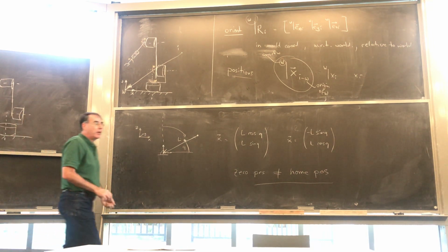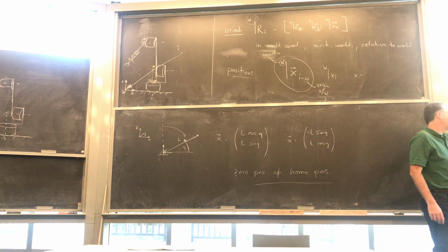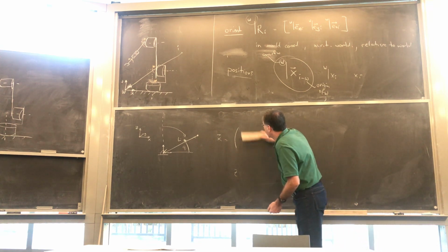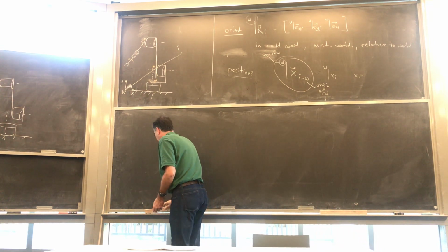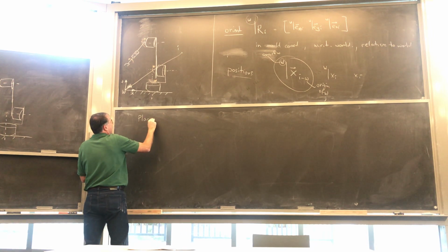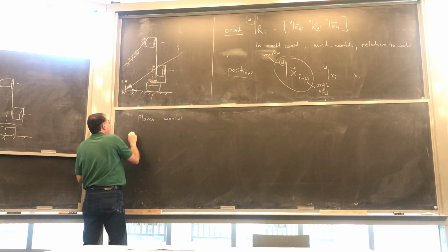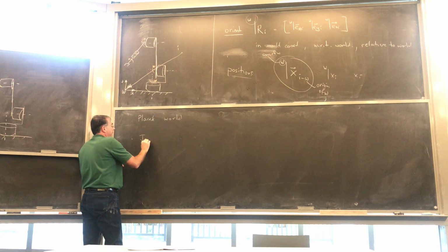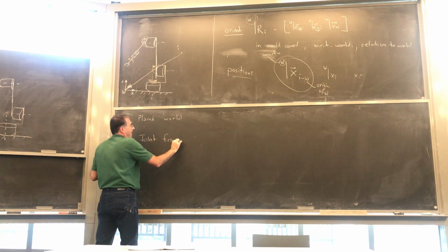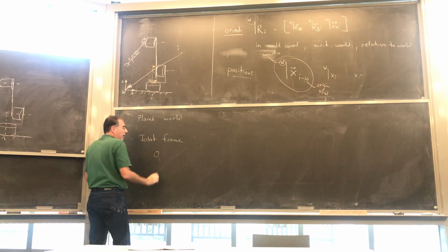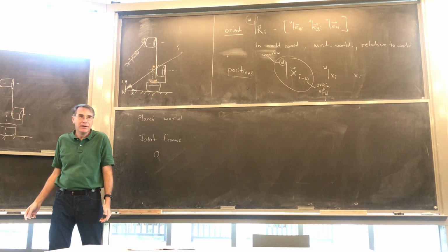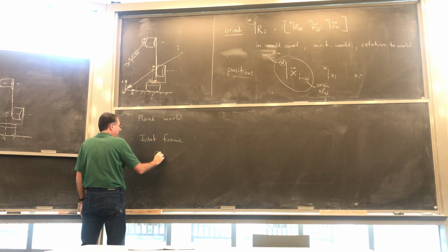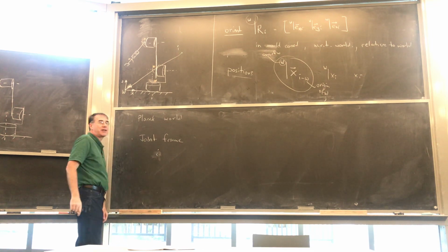So, step one, we've defined our zero position, we've defined our reference, and now we need to go through and get all of our coordinate frames. So I've placed the world coordinate frame. Now I'm going to put a joint frame at each joint. But I'm going to do two things. Do you want to start numbering at 0 or at 1? It's arbitrary, right? So I'm going to call it joint I for a second, but then I'll start at 0.